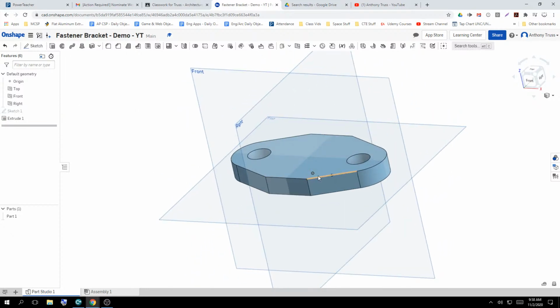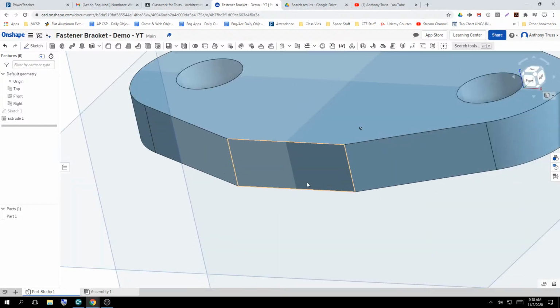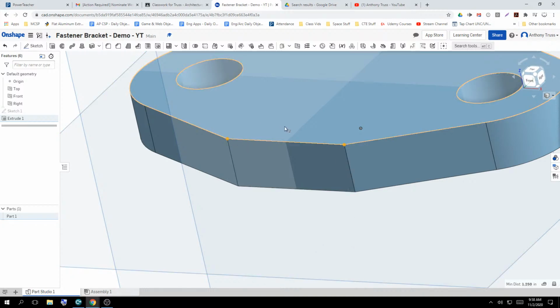Now I also want you to take notice. You know where these rectangular tabs are going to come. They're going to be from that point to this point, right? So the rectangular tabs are going to come off of already known existing locations on our model. So at this point, all I have to do is snap a rectangle to these 2 points and specify the depth of it, which happens to be 1/2 inch thick, right? And then go up the right height.